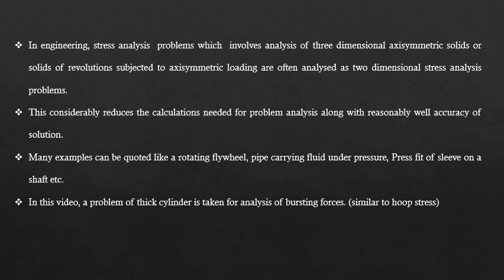In engineering, stress analysis problems, which involves analysis of three-dimensional axisymmetric solids or solids of revolutions, subjected to axisymmetric loading, are often analyzed as two-dimensional stress analysis problems. This considerably reduces the calculations needed for problem analysis, along with reasonably well accuracy of solution.